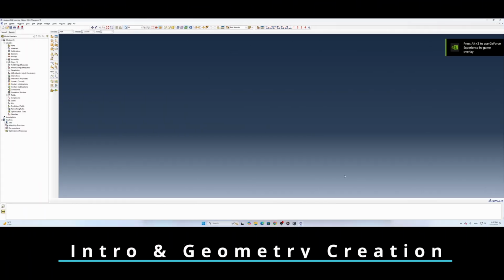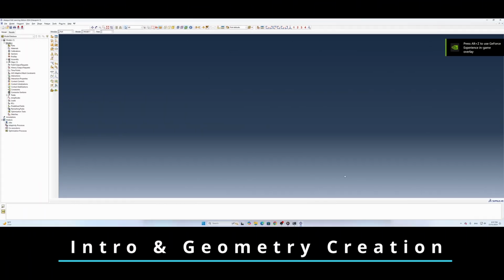Hey guys, in this video, I'm going to show you how to perform a ductile damage simulation using Abaqus. In this model, I'm going to have a ball travel at very high velocity to penetrate a piece of plate. To do that, let's create the parts first.